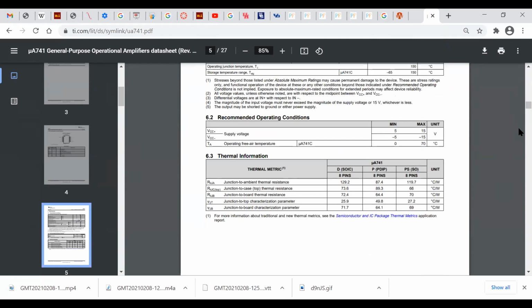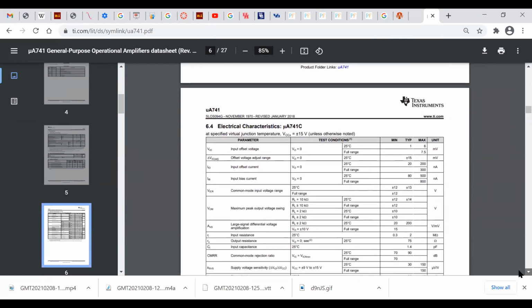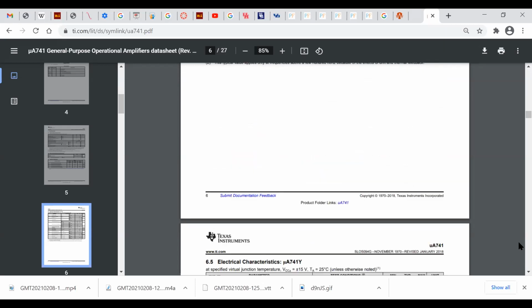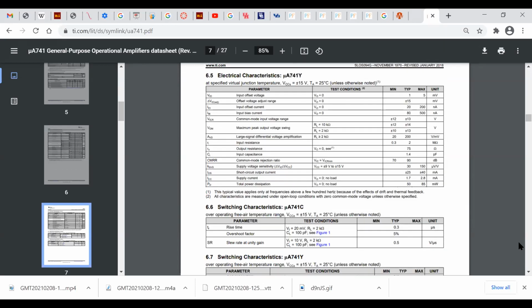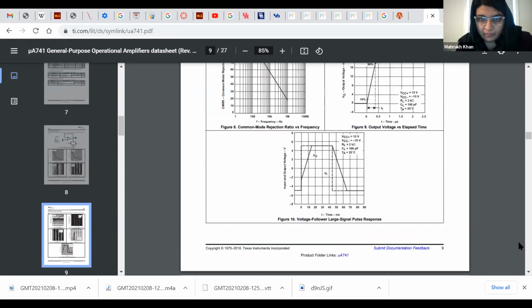What you said earlier, that open loop op-amps are always going to be saturated one way or the other. Yes, that's what I'm trying to say. So the output is going to be binary, either plus VCC or minus VCC. Yes. What I'm saying is if their supply voltage is lesser than their open loop gain, then it will always be in saturation.